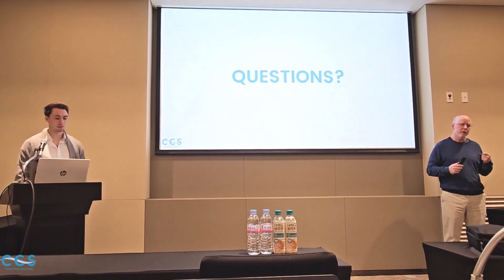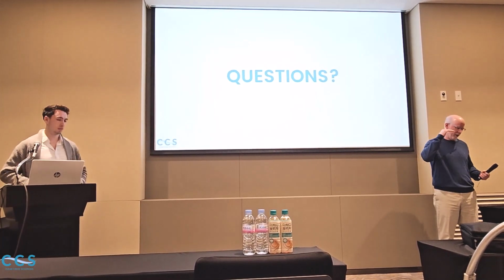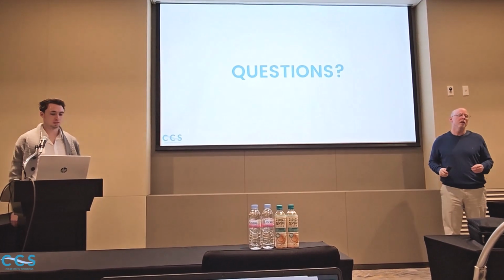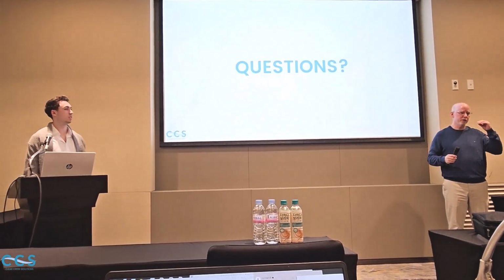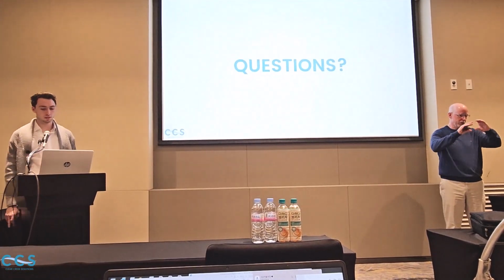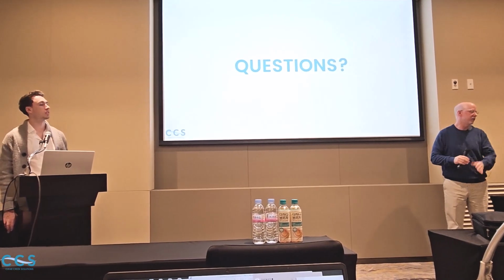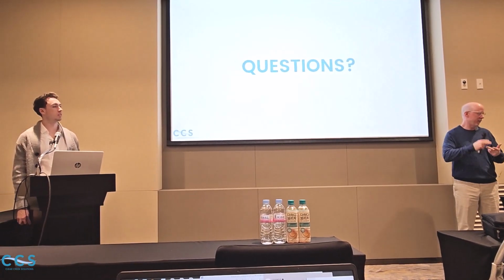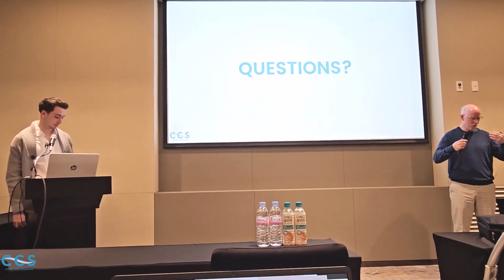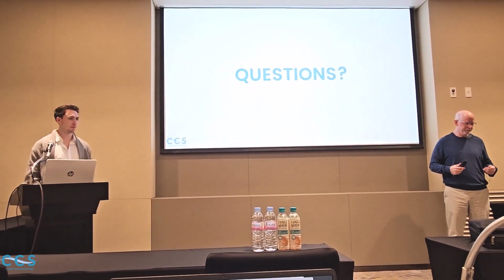And when you do it in HSPF, you have an order of the things you have to model. Some constituents you can model just that. Others you need temperature, you need dissolved oxygen, you need a whole list of parameters.